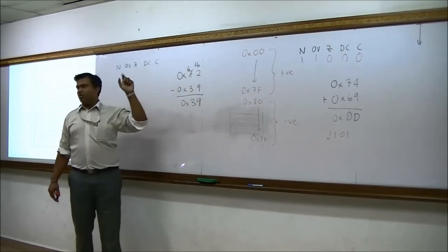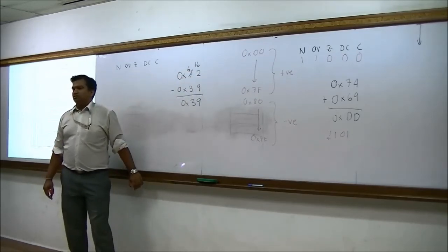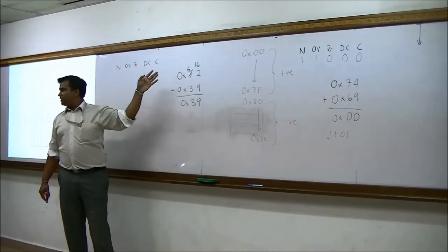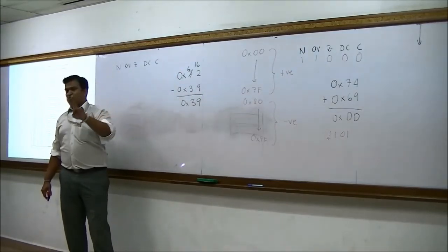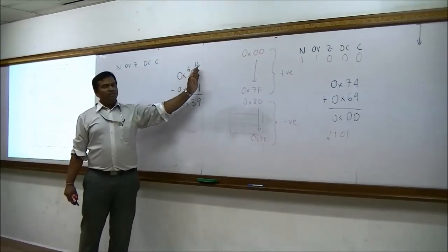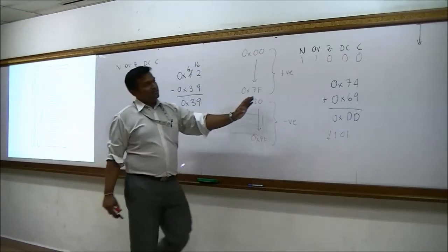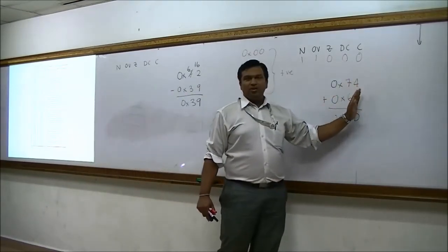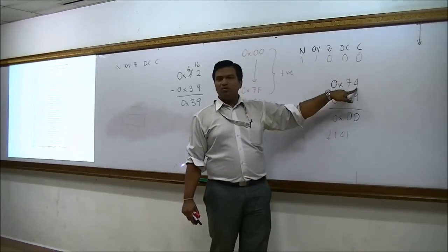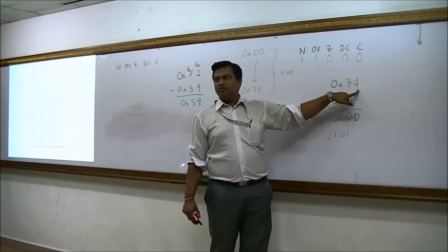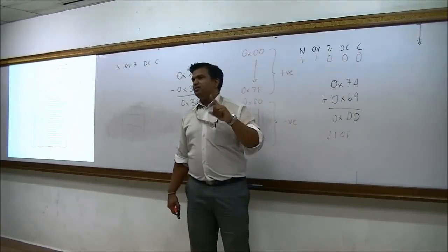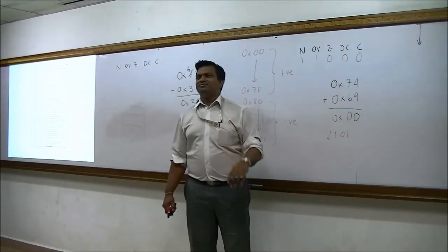So my question is, do we have borrow? No, we don't have borrow. This guy never borrows from the other guy. Do you understand or not? There are two: borrow and digit borrow. Digit borrow is like digit carry. Digit carry is the lower nibble adding, causing a carry to the higher nibble. Do you know why each number is one nibble? 4 bits make up 1 hex digit. Those at the back, can you all understand?